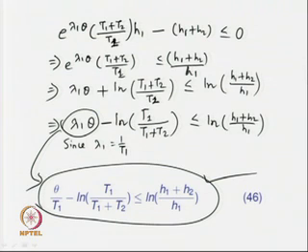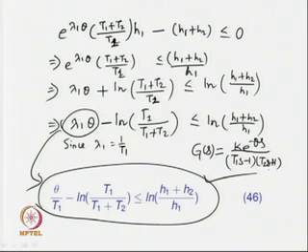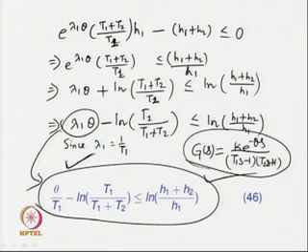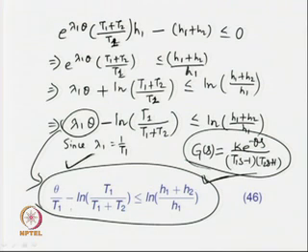If the system dynamics is of second order, again let me repeat. Given a system of the dynamics of the form k e to the power minus theta s, with T 1 s minus 1 and T 2 s plus 1, so this is the dynamics of the original system. Then the conditions on theta, T 1, T 2 and so on, that are given over here, have to be met to generate stable limit cycle output, or indirectly speaking, the relay will be able to induce stable limit cycle output, provided this condition on theta and the T's are met.